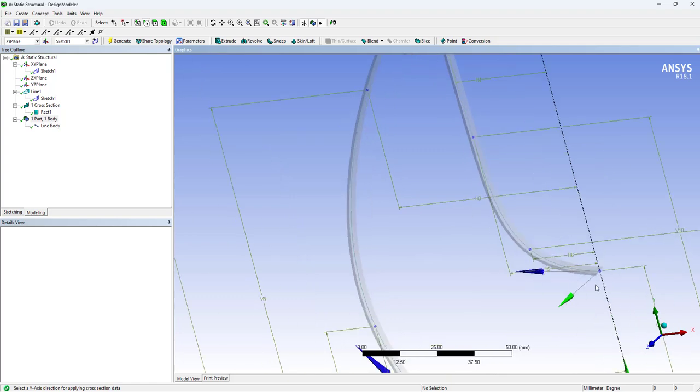In order for the part to be symmetric, out of plane rotations are restricted, and in plane displacement is free. So I'll say that if this part is symmetric about the y-z axis, the deformation or deflection in the x direction will be restricted here.